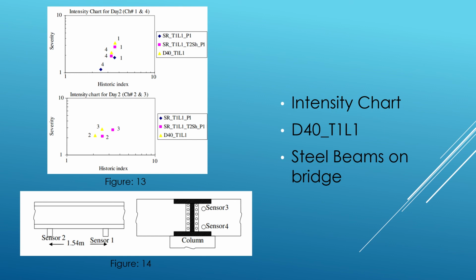Another case study was performed on the steel structure of the bridge as well, to learn more about the AE process and the condition of the bridge itself. For the steel components, the threshold of the bridge must exceed 40 dB. If under that, the sensors would not pick up the signal.